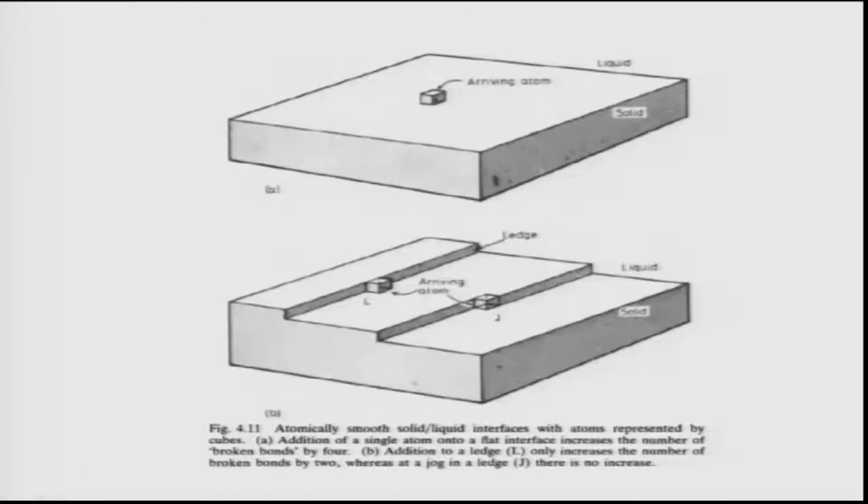As you see here, there is a ledge on the surface. This ledge forms because of surface nucleation, which I discussed in the last class. The ledge can also bend and form a kink, and because of these kinks, atoms from the liquid can arrive and sit on these positions, marked as J here, and make further progress of this step in this direction. Slowly the steps will move like this, so one layer of liquid is converted into one layer of solid, and then it goes further.